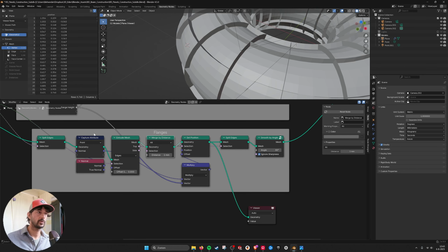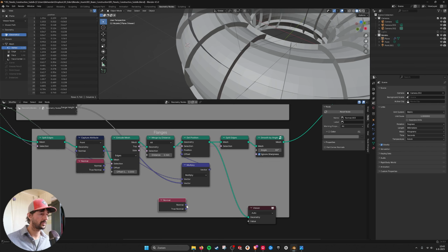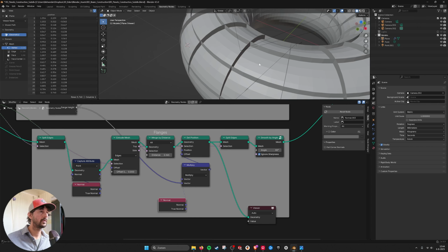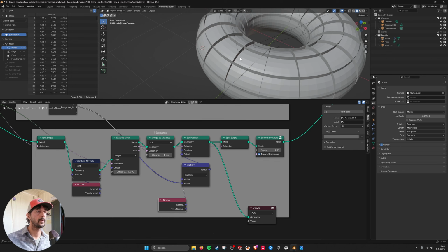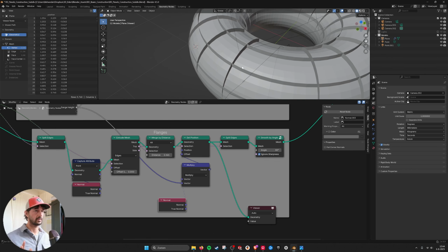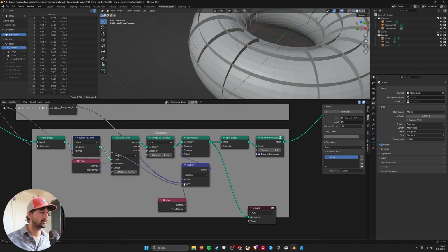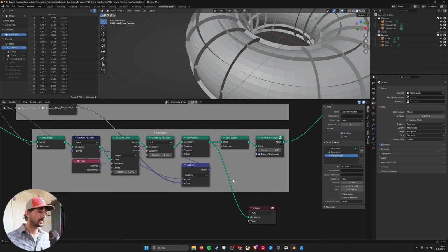Then I'm setting the position to the normal that I captured here. I have to capture the normal here because if I use the split or the extruded normal, then you can see what happens. I get this, let's see which line it is. It's the top line. You see that they don't take the right normal because it doesn't remember what direction the edge was going before I split the geometry. So you need to capture the normal here. Let's delete this one.